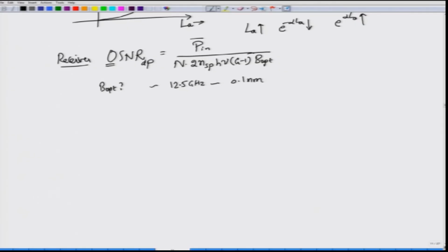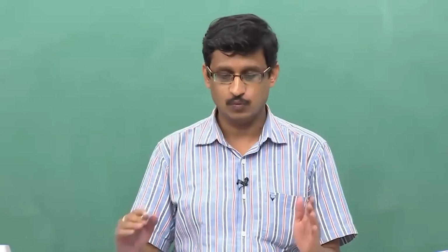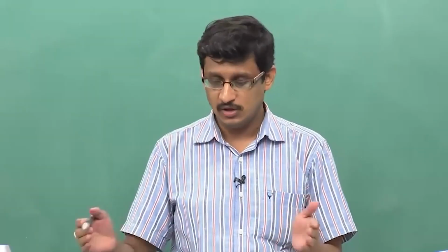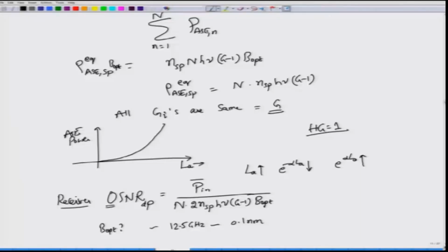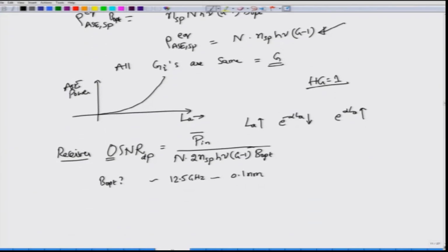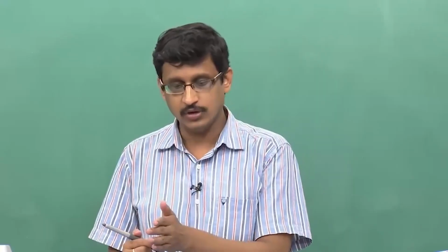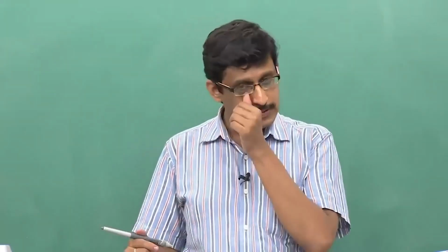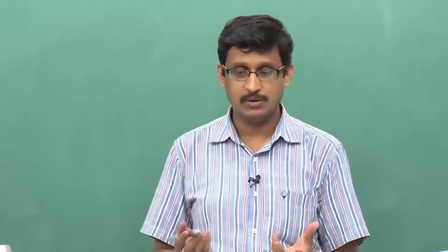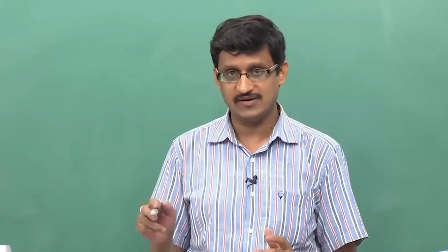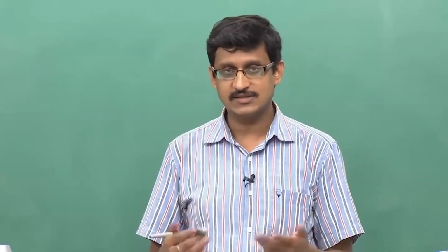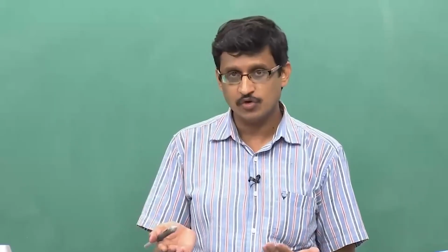So, we have looked at what happens to the ASE. We have looked at an optical communication system with multiple noise sources. What you can see here is that the noise spectral density actually starts growing linearly with respect to N. If you were to consider just the receiver side after a cascade of amplifier stages, if you just put a photodiode and then detect the signal, you will see that the Q factor actually depends on the inverse square root of N. As the number of stages N increases, the launch power also must be increased.